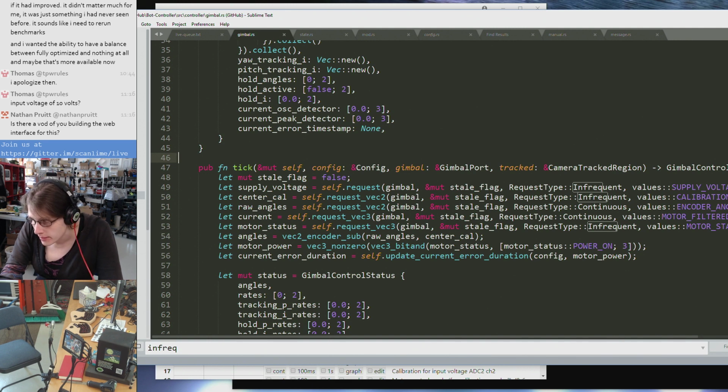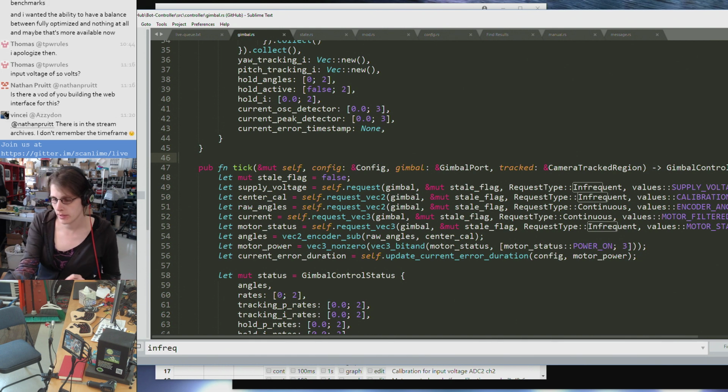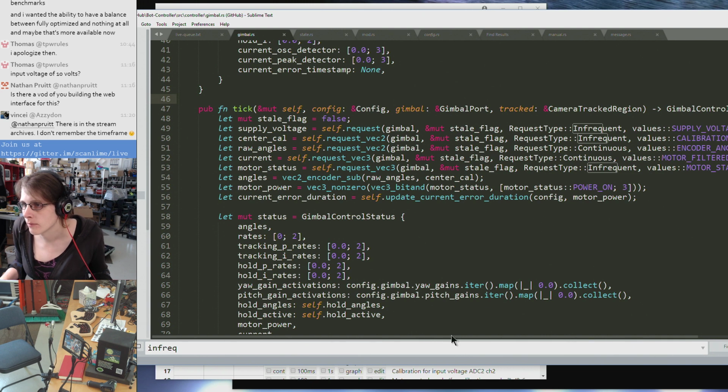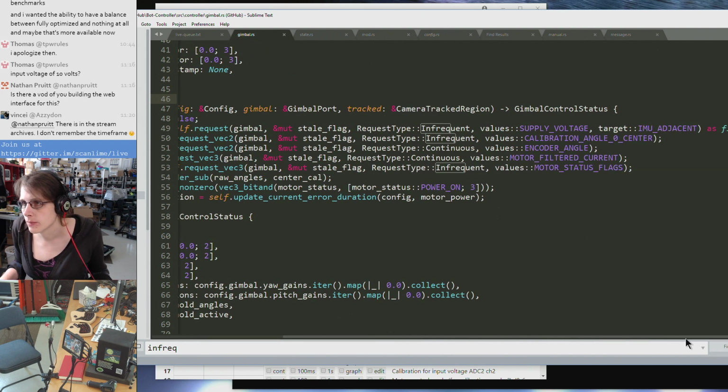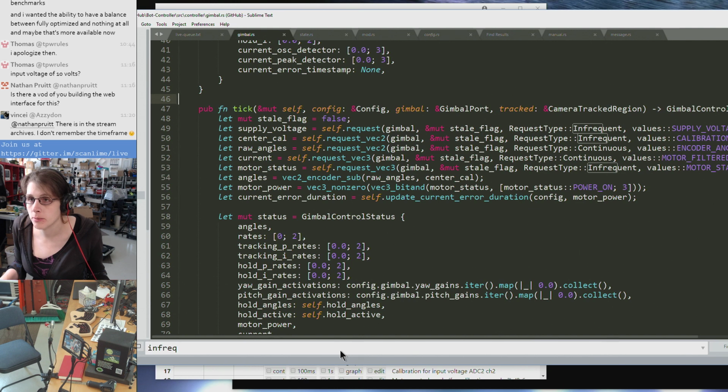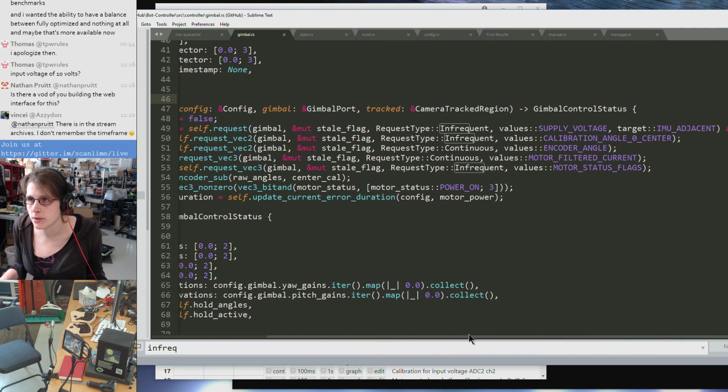That said, given we are actually pulling so much of this, because it is a control loop, I'm actually not that fussed by maybe just every time we hit this 250 hertz tick, taking a look at the timestamps on all the configuration values. I think that is actually a pretty reasonable thing to do at this point. And one side effect there is that when the config changes, you'll get a pretty rapid response with the gimbal changing, so it'll be pretty natural to update those parameters.